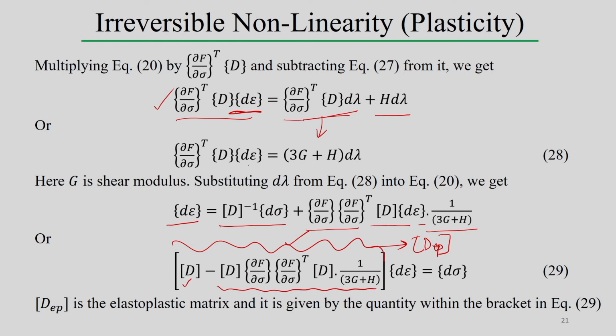Also, even if we look into the recovery part, even if we assume the material behavior follows elastoplastic, in that case even in the plastic domain, if you release the load, some recovery will be there. That recovery is the elastic recovery. So, since it is associated with some sort of elastic recovery, the analysis should be considered the elastoplastic analysis, and accordingly the DEP, the elastoplastic matrix, has to be considered even if we do the analysis in the plastic domain.